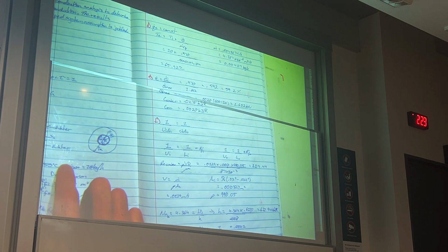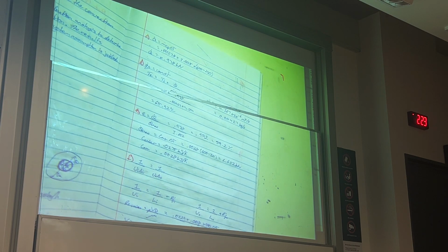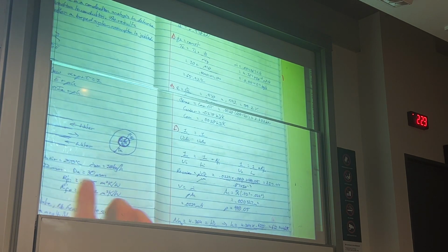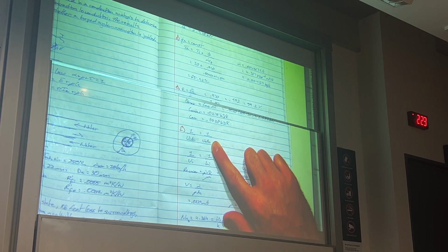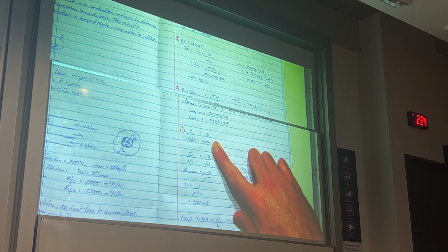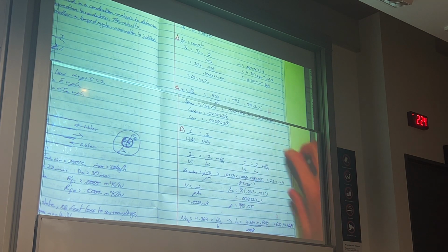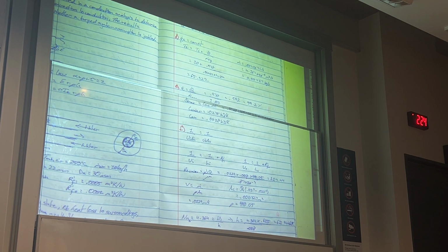And then we want to determine our heat transfer coefficients at the inner and outer tube surfaces. So I've used this relation here, and we were told that the thermal conductivity of the steel tube is constant at 35 watts per meter Kelvin. And we're given fouling factors, so we can use these relations here.